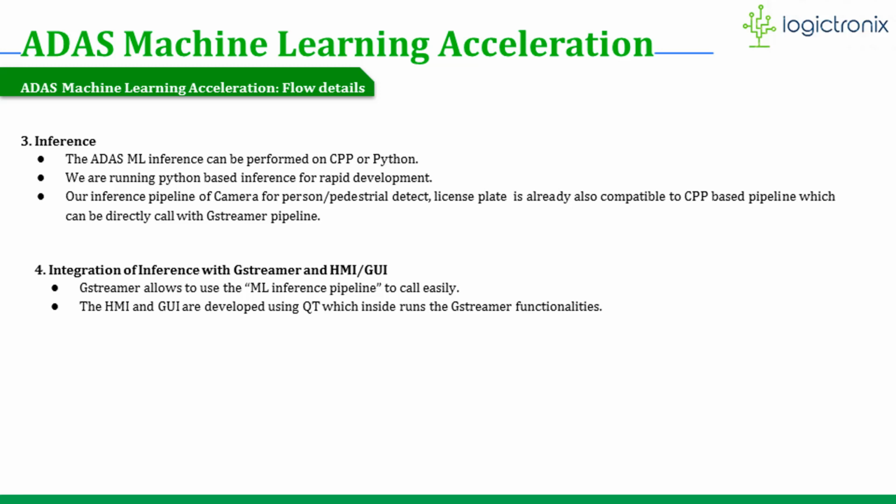We can use either inference application, and the one we are targeting is going to run the DPU, run the trained XModel over the DPU, and create the bounding box information. That bounding box information is processed by the MPSoC processing system, or PS, and it will create labels, counting information, and detection of specific bounding boxes on the given stream. This is just one pipeline, and we can run that specific pipeline with GStreamer. GStreamer is also supported by the